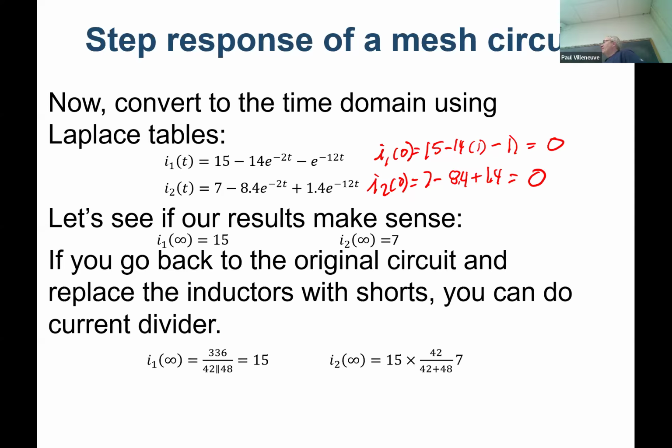And the benefit is, remember how we had to do all the circuit analysis before? Draw the circuit at t equals 0 minus, draw the circuit at t equals 0 plus perhaps, and then draw the circuit at t equals infinity, and then do all these calculations. Over here, you just draw one circuit and you do whatever circuit analysis, and it gives you the time domain equation for any period in time.